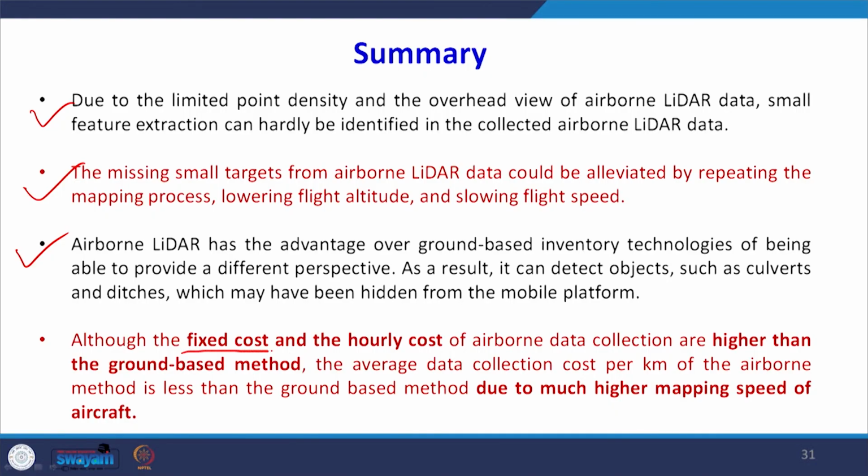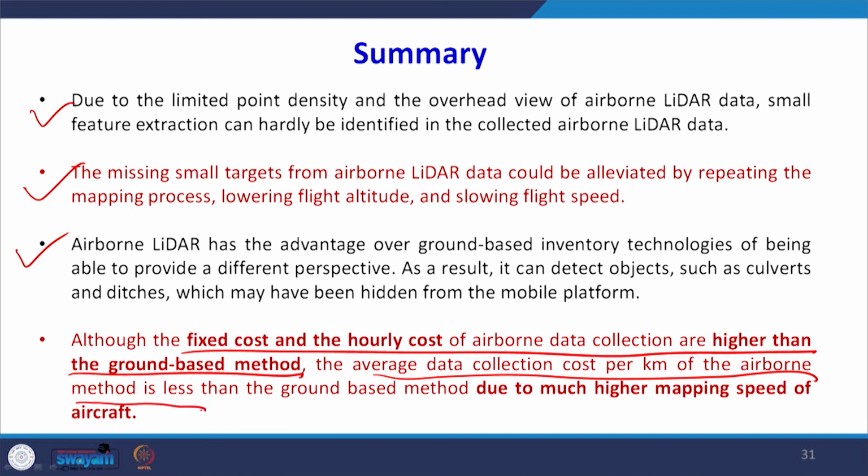Now, if we look at the cost factor, if we have to hire the system and somebody else has to collect the data for us, the fixed cost is there, but the hourly cost of airborne data collection is much higher than the ground based method. So cost wise it becomes a little expensive, but the average data collection cost per square kilometer of the airborne method is less.